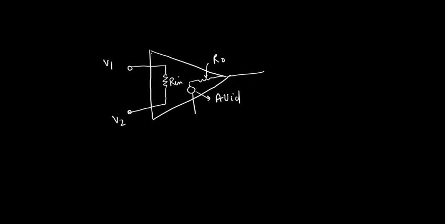So at the output, we see some voltage even though there is no input at V1 and V2. Correct? So that is called output offset voltage. This is one electrical parameter or electrical property in output offset voltage. So let us say X is the voltage difference which appears even though you are not applying any input.